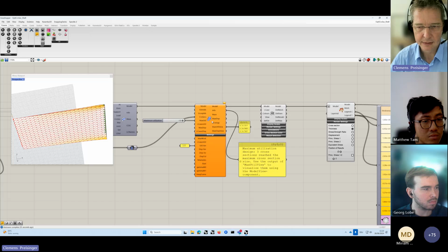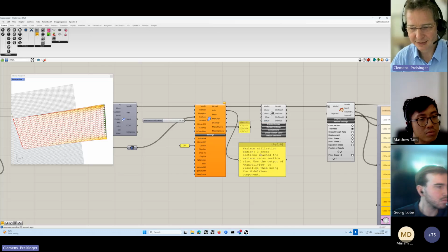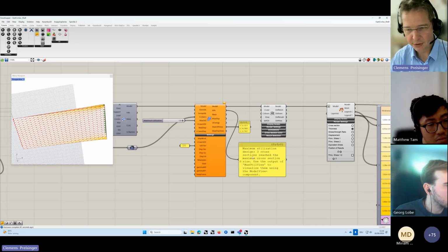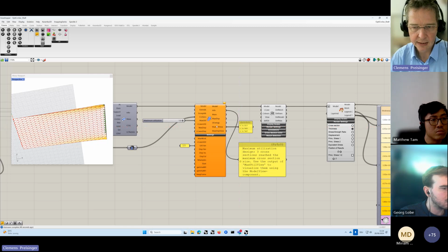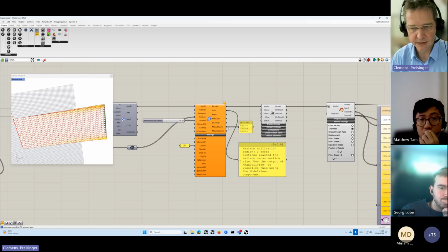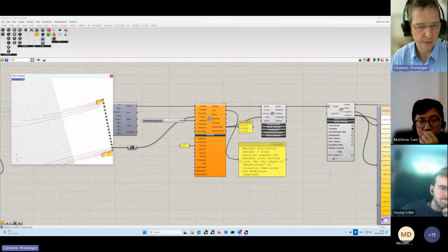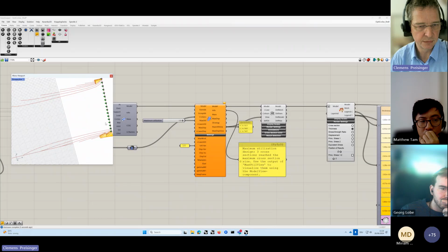And since in shells there are always points with some kind of stress singularity, the design component tells me that there are 3 cross-sections which have reached their maximum cross-section size. And if you wonder now which those elements are, at the max util view output, I get now the shell index and the corresponding mesh face index. And if I plug this into the model view on the view, I get now those 3 elements which are